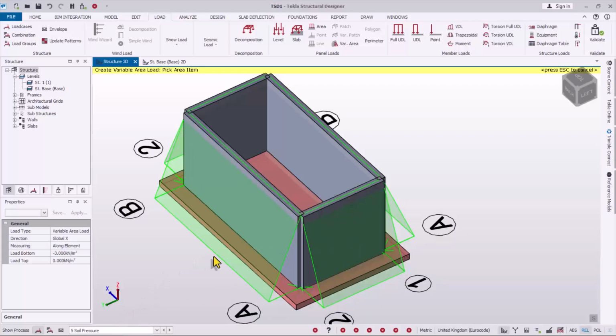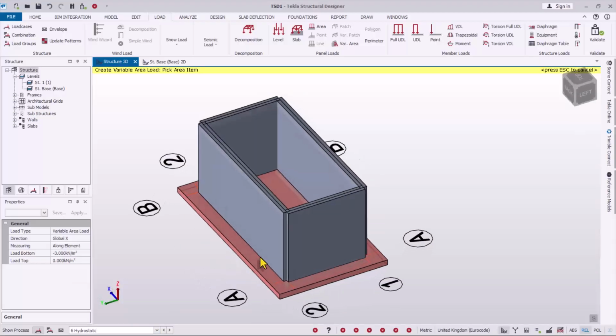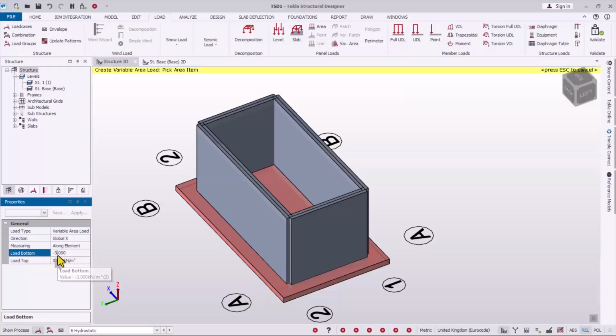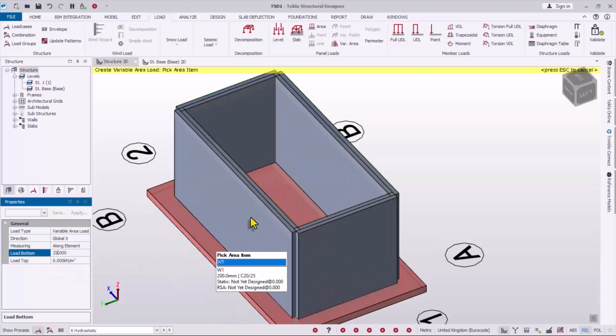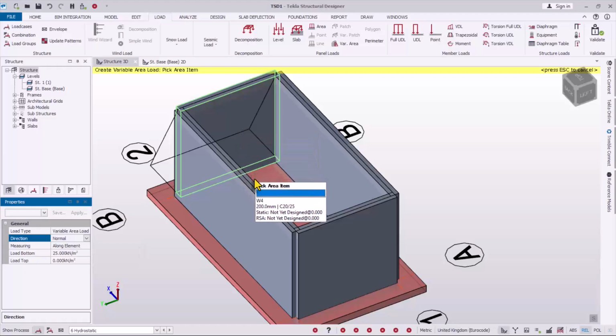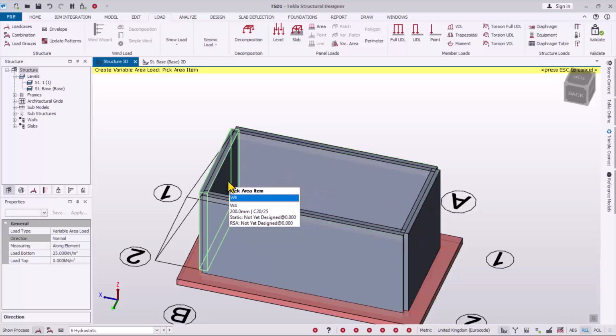Okay, so the next pressure we are going to be applying, which is the major load, is the hydrostatic load we are going to be applying. Okay, so we escape from this load, and then we use also the varying load. So for the hydrostatic load right here, you will be having it to be 24, or we used 25 kilonewton per square meter right here as the load at the bottom of the swimming pool. And then over to the directions, we use normal, so we just have to click to have it applied successfully. We wouldn't want to apply it outside, but we want it applied inside.